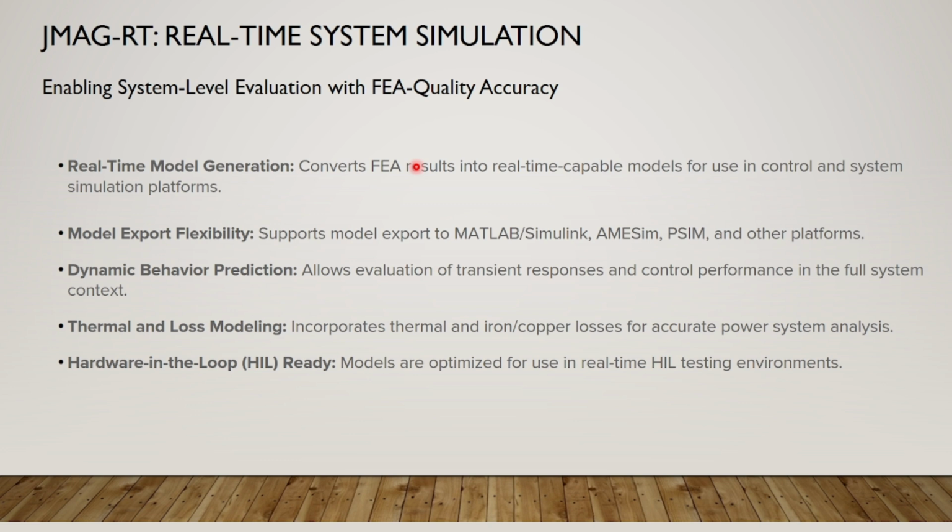So if you need to control the motor with your controller, for controller behavior operation, your motor input can be pulled out using your FEA results and pushed using Jmag RT to your MATLAB. In MATLAB you will design the controller and you can directly couple the controller with your designed model using Jmag RT, and simulate in your MATLAB model itself. So this is also possible using Jmag RT.